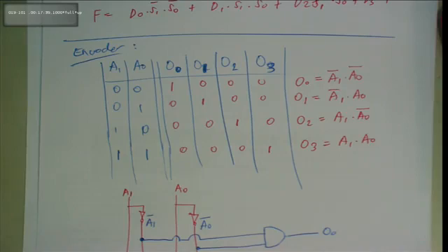And you want to have, let's say, 16 lights, 16 LEDs, right? So what sort of decoder will you have? 16 LEDs. What will you be using? At one point in time, only 1 light turns on, right? So you'll have a 4 to 16 decoder, 4 to 16. How do we know 4? Well, 16 is 2 to the power of 4.